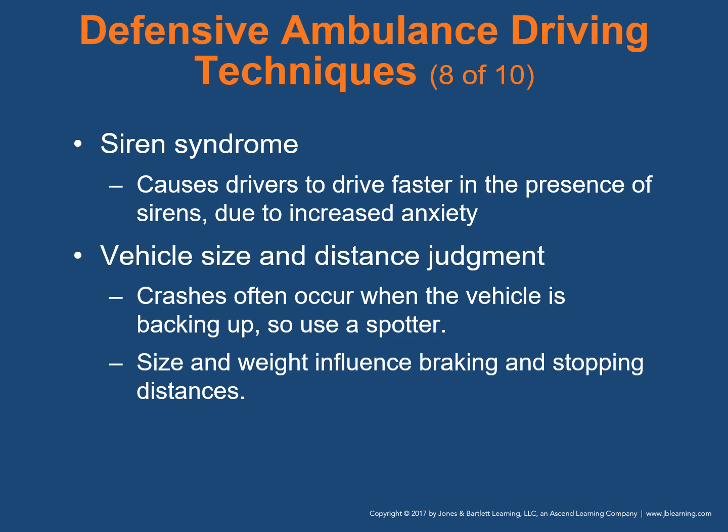Now let's also talk about vehicle size and distance judgment. Awareness of your emergency vehicle size and weight improves your driver's ability to maneuver and judge distance. Crashes often occur when the vehicle is backing up. Always use someone outside the ambulance as a ground guide when you're backing to avoid any incidents. Vehicle size and weight greatly influence braking and stopping distances.